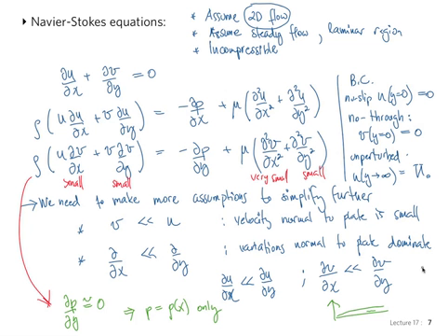We could find them. In fact, for the flat plate, if the streamlines are completely horizontal, the pressure is constant, and the pressure for a flat plate is constant everywhere in the boundary layer. There would only be variations in the pressure if there were curved streamlines, for example, if the flow was going around an airfoil or something. But for the flat plate, the pressure is constant everywhere in boundary layer flow. It drops completely out of the unknowns.